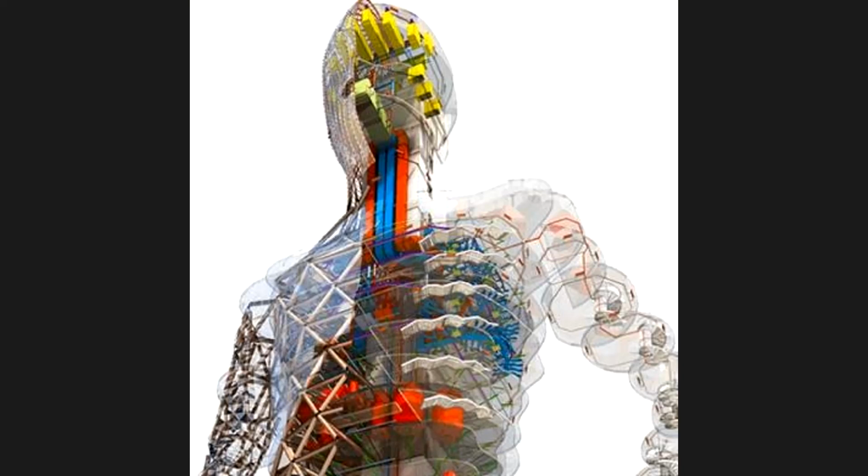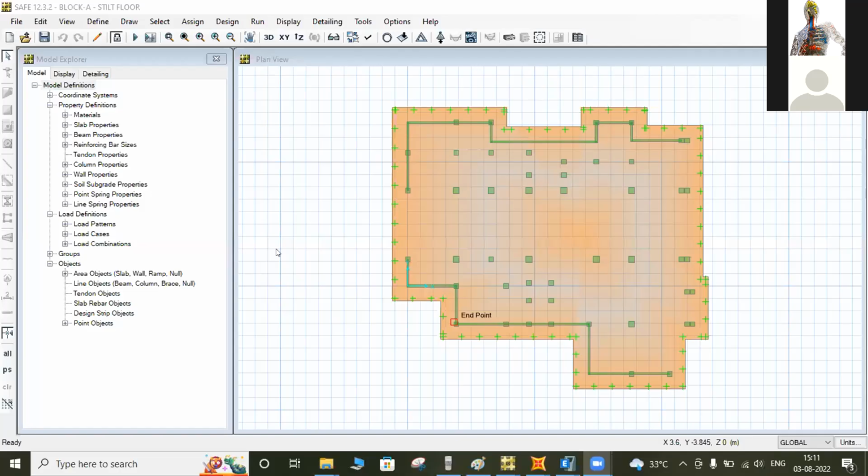Okay, sir. First of all, we have opened the foundation part, sir. Sure, so we have shared the screen. Basically, it is the substructure part for this project. The previous one we opened was the superstructure; this is the substructure part. So we are exporting the reaction forces, and when we import them, after that we have to perform the modeling for the substructure part, whatever the materials for the raft, isolated or stiff property we have made, and some retaining walls.